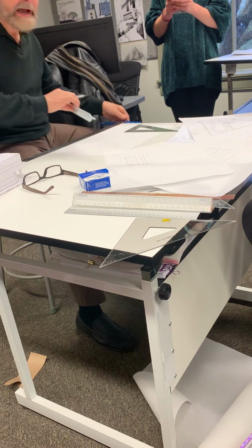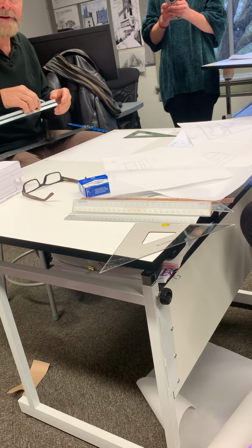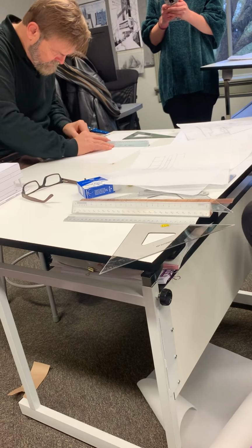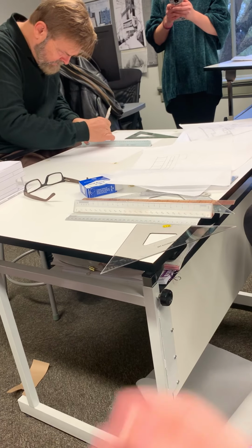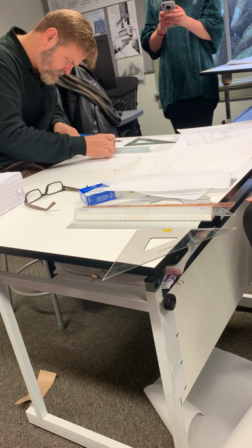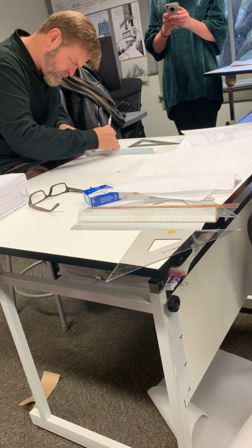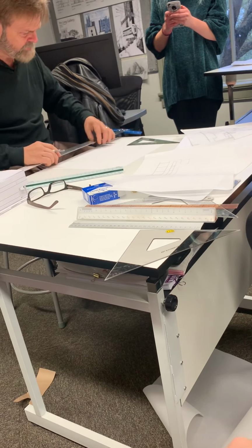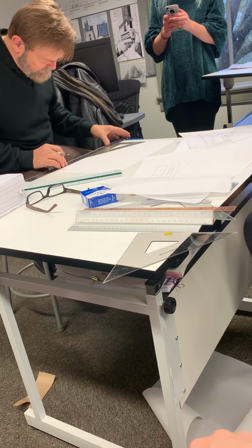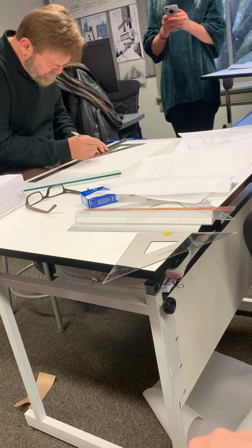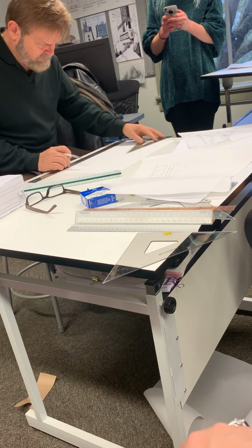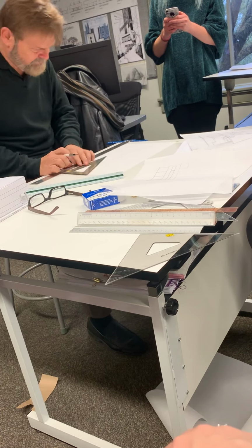Okay, and then now I know that this roof is flat, right? So all I need to do is lay out this dimension here. So that would be 21.2 there. Okay, so now 22 right here, so you can see how it's coming, and 22 and 10 inches. There. Okay, and then flip.